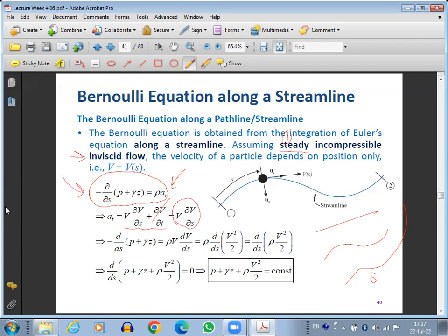Application comes when there is relative motion between the layers of fluid. Okay. So we are already starting from the Euler's equation. So this condition is already there in the inviscid flow condition. So condition number 2 is already there. Again, we put a condition of steady flow. So ∂v/∂t is cancelled. So these are the two limitations right now we have imposed. Okay.